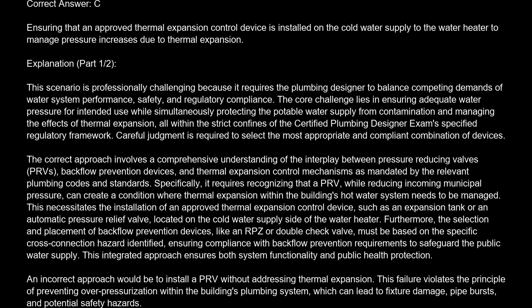The correct answer is C. Ensuring that an approved thermal expansion control device is installed on the cold water supply to the water heater to manage pressure increases due to thermal expansion.